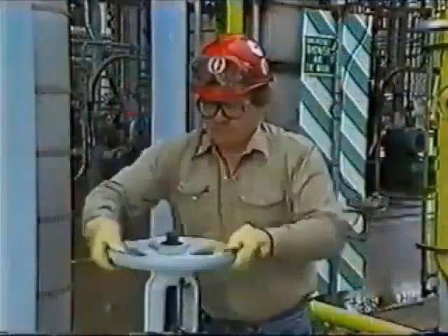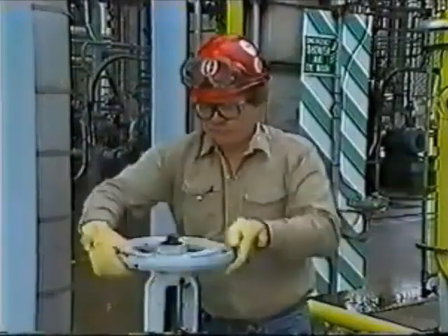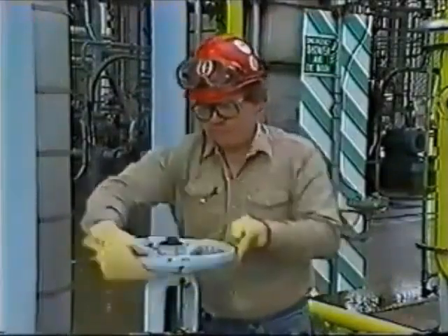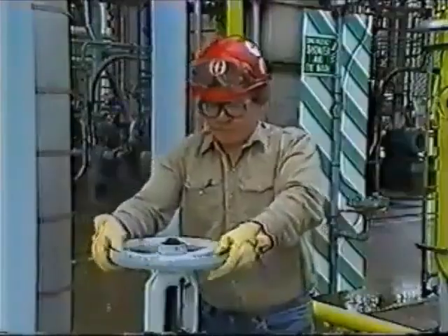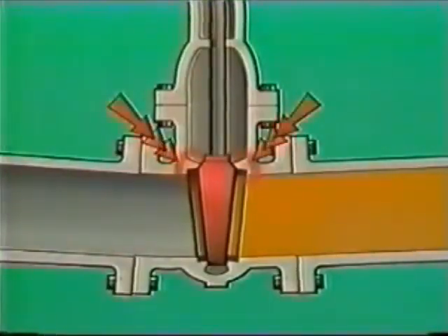When closing a valve, you should avoid using excessive force because this may damage the seats or the flow control element. This is especially true for gate valves in high temperature service. After the valve is closed, it cools and the valve body contracts. If the gate is already jammed into the seats, contraction of the valve body may cause the gate to bind.